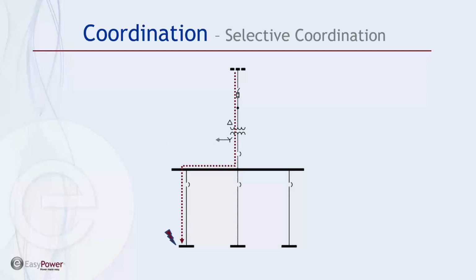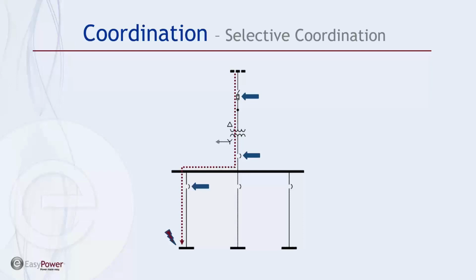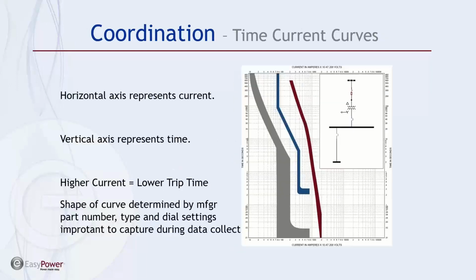So in this case, the feeder breaker, the main breaker, and then the fused primary will see that fault current. And ideally, any of those three could open or clear the fault, but there's a downside depending on which one is chosen, because if the fuse goes first, then we're going to lose the whole plant. If the main breaker goes first, we're going to lose several other feeders. So ideally, the device that we want to clear the fault is this localized feeder breaker.